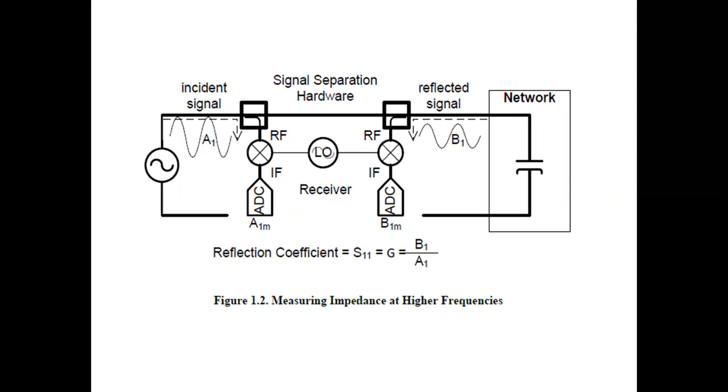The RF and microwave S parameters provide complete insight into the linear behavior of the RF and microwave components, and they are independent of the characteristics of the VNA itself. Since the VNA calibration and impairments of the instrument are completely removed from the measurement, the S parameters are an extremely accurate representation of the linear behavior of the component under test, describing how it behaves and how it interacts with other devices when it is cascaded.